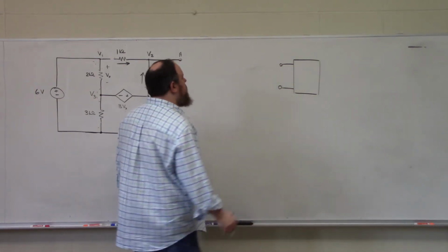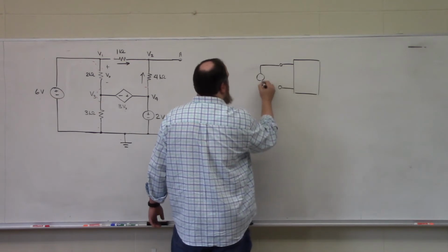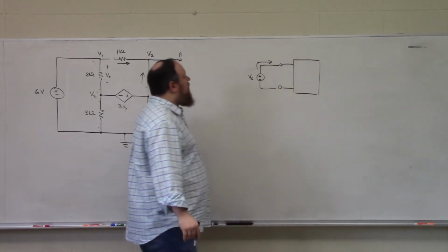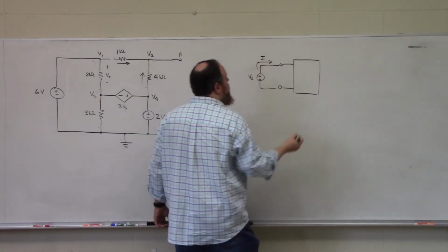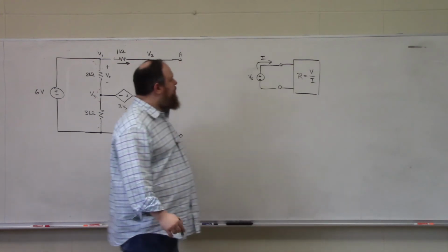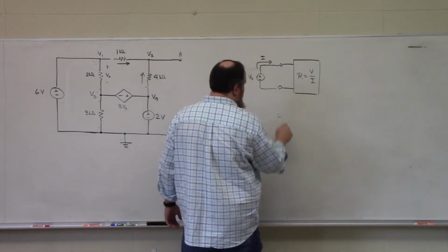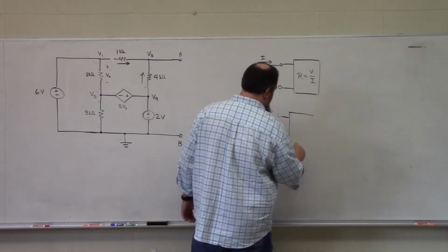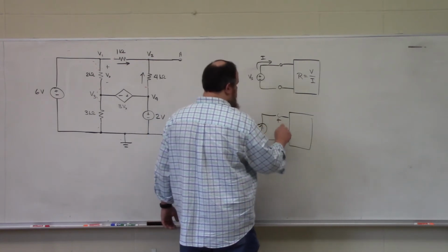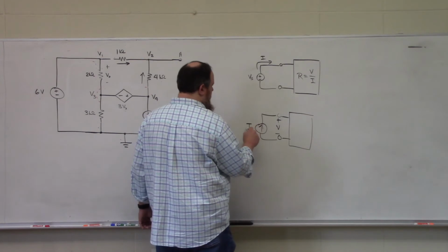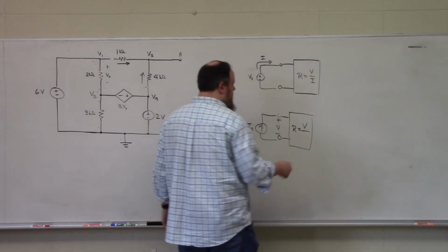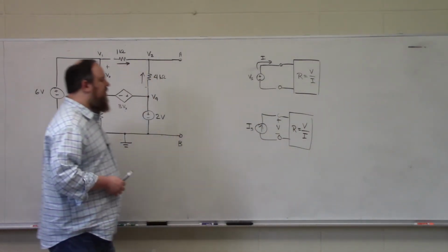You may recall from our lecture on Ohm's law that if we have a 2-terminal network and we hook up some voltage source to it and measure the current flowing into the network, the resistance of the network is simply V over I. And similarly, if we have the same network and we hook up a current source and measure the voltage drop, we would find that the resistance is, again, the voltage drop over the terminals divided by the current flowing into the network, or V over I.